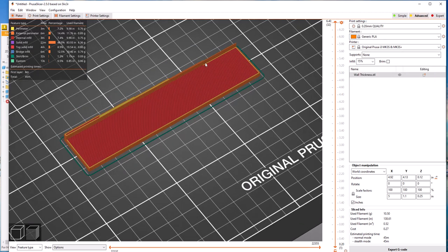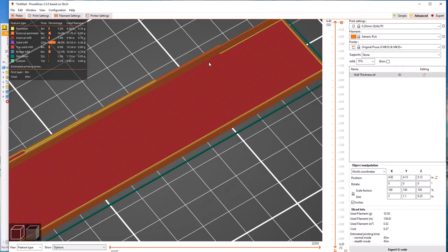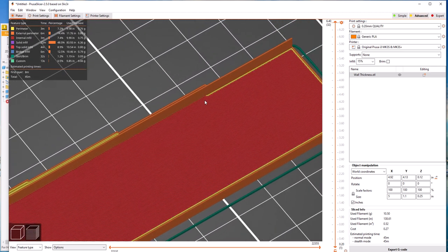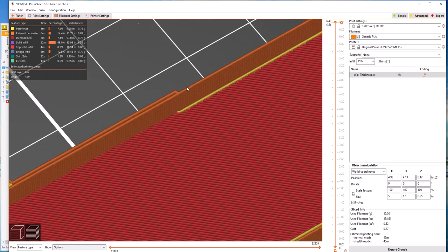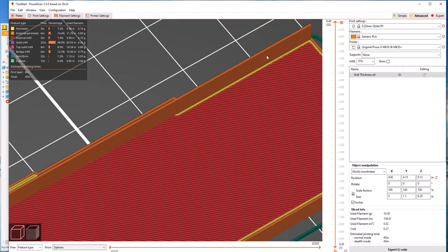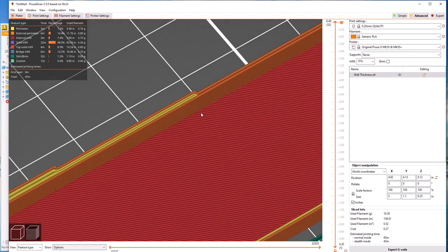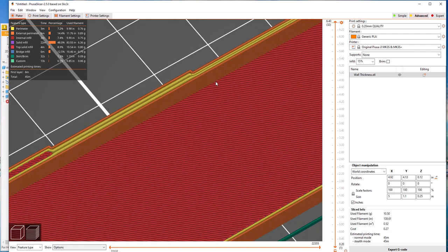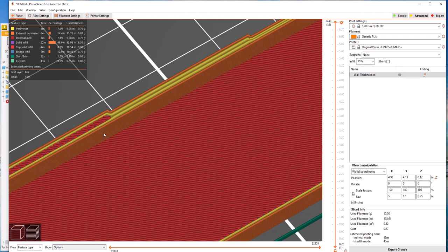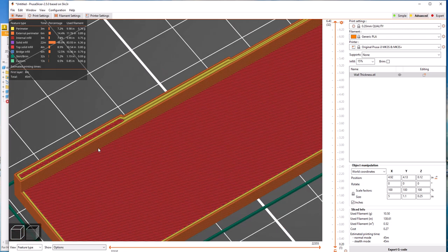But if we come into the wall thickness here, which is why I have this print right now, this 0.02 wall thickness is really only getting one layer of filament wide. So it's not real strong, it's not working out real well. As we step up to 0.04, we are getting 2 walls. And then we go up to 4 walls, 4 and 4. And that's because we have our settings set at 2 wall thicknesses on the perimeter. So what does that mean?